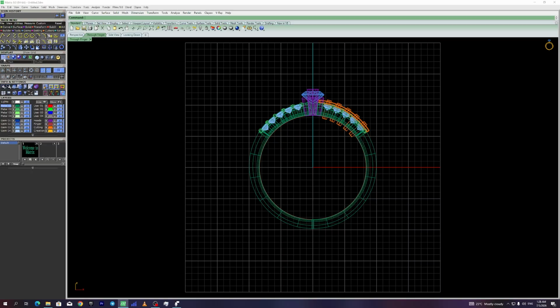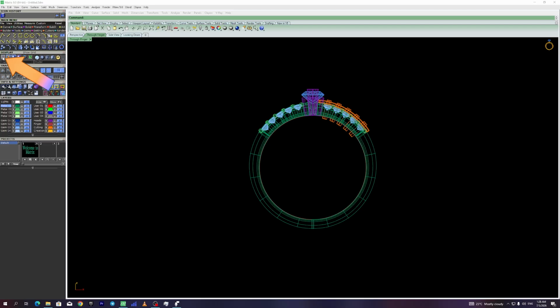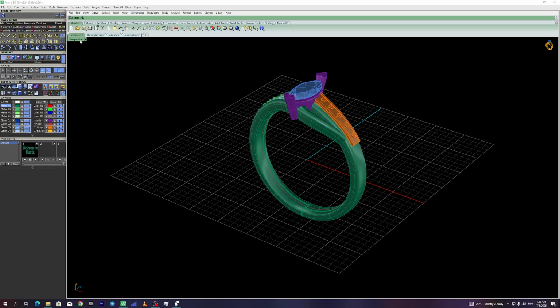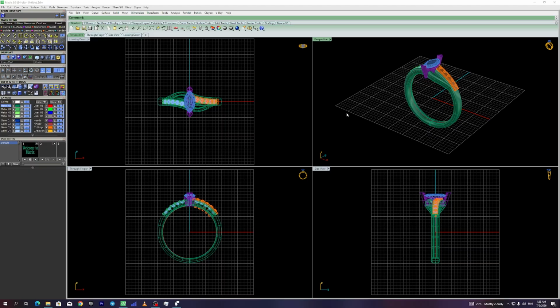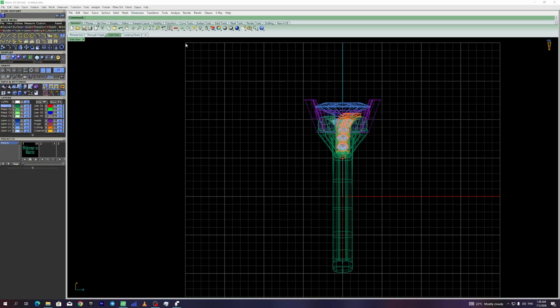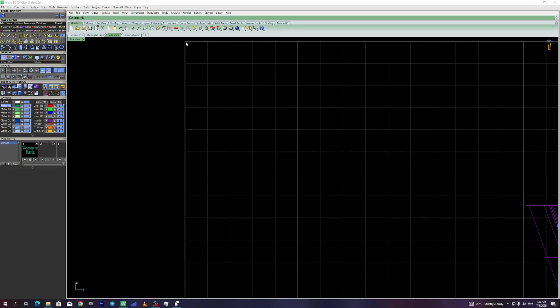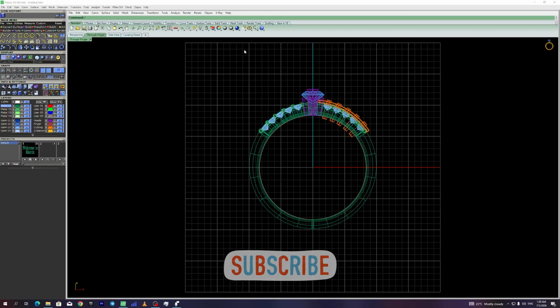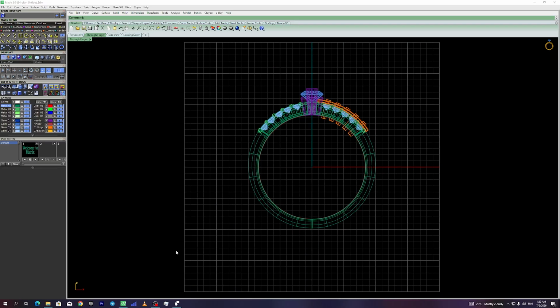Finally, let's talk about the grid, the chessboard-like pattern you see in the viewport. We call it the grid, or sometimes a C-plane, which stands for construction plane. If you look closely at the grid, you'll notice it's made of light and dark gray lines. The light gray squares are 1 mm each, and every 5 mm you'll see a darker gray square, which makes it easier to measure the distance visually. The entire grid is about 16 centimeters across, which gives you a nice workspace to start your designs.